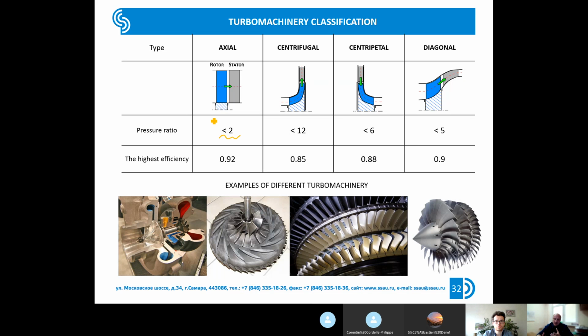How to determine it? Because usually such information is not provided in publications. So you could find out an approximate value of the pressure ratio of the cascades, and people who provide the thermodynamic calculation usually use the value 1.35 as the average pressure ratio of one stage of the gas turbine engine.